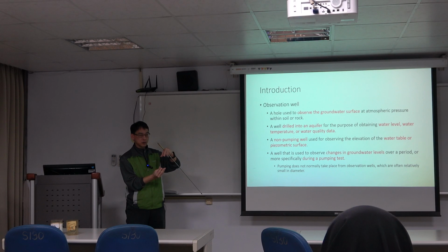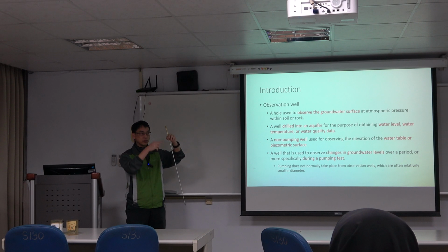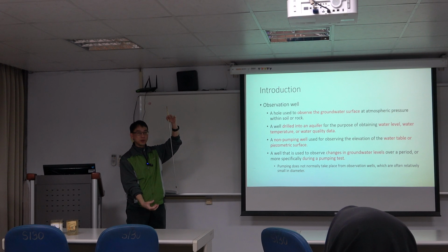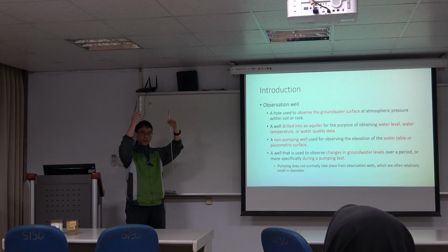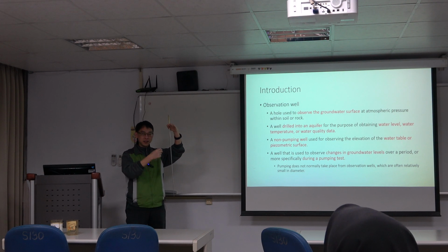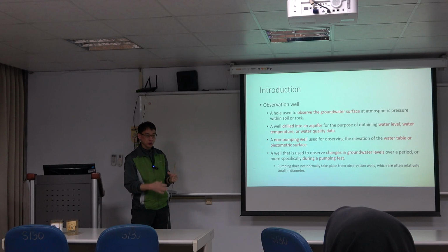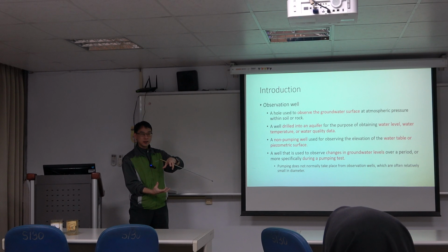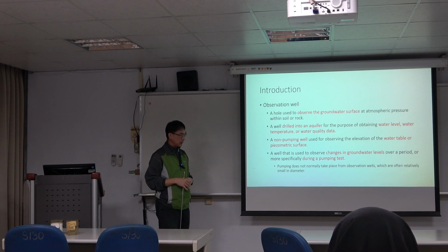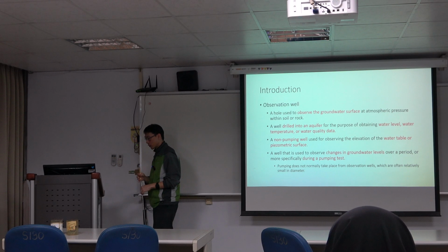The small one will be relatively small, but commonly, if your depth to water is very, very deep from the surface, you need to use a stronger pump, and then you will be able to take the water out. If the power of the pump is not sufficient, it is not able to take water out. And if you want a more powerful pump, you need a relatively larger size. That will constrain you, you need a larger borehole, and then you will be able to put the pump inside.